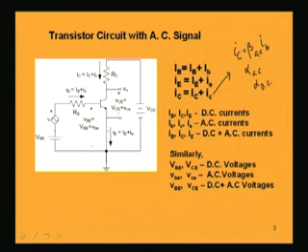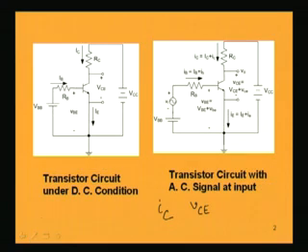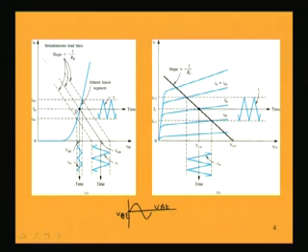That will happen when the IB current is 0, and the maximum value of the IB current will occur when the base to emitter voltage is 0. So, that is another maximum point. If we join these, we can get the load line, and for a particular value of IB, or for a particular value of RB, the intersecting point between the characteristic and the load line will give you the operating point, that we all know.